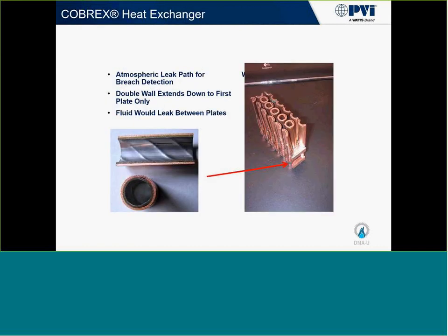And because we did that, they're a lot lighter. We can put them into an extremely small footprint. The heat exchanger inside the COBREX unit, the steam is actually in the tubes and water's in the shell. That's important for a bunch of reasons, especially if you get into adverse water quality conditions with hard or aggressive water.